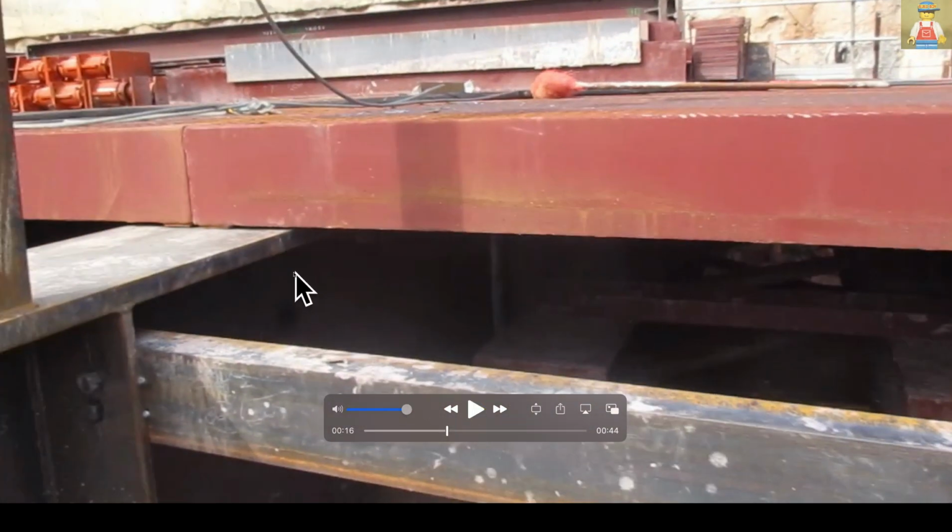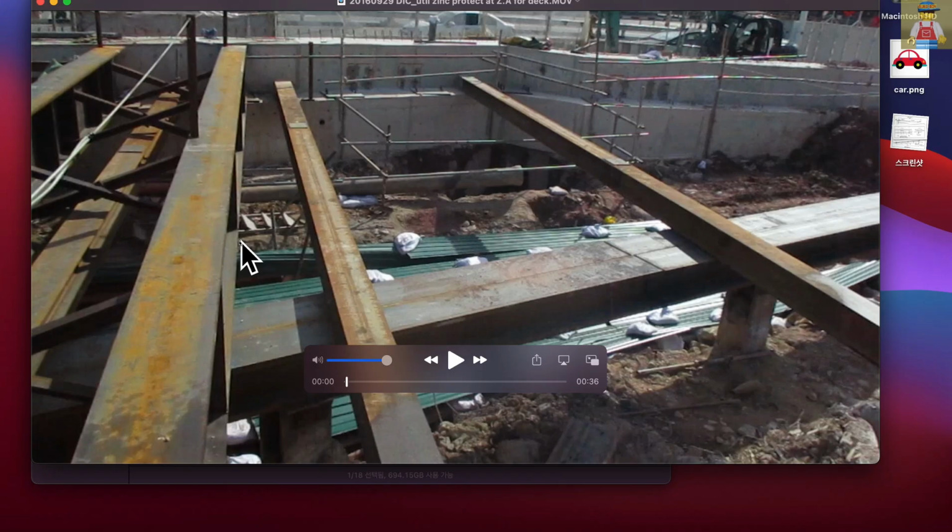This is that, you can see clearly the decking support beam and a piece of deck every 2 meter, sheet on top. Then later on, vehicles will run on top of the decking plate. And as you can see, every deck support beam is 2 meter. In between, if there is a strut, we install the strut. If there is no strut, then you can see this USB, utility support beam, every 2 meter. So this is 2 meter, and USB also 2 meter.